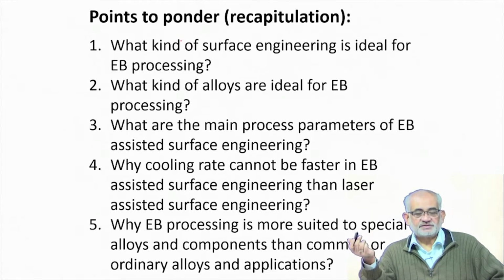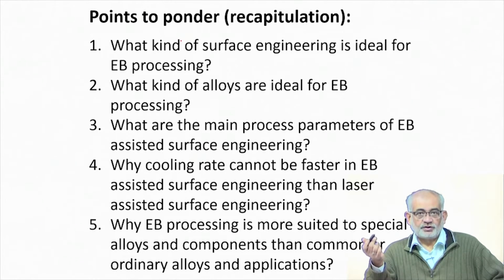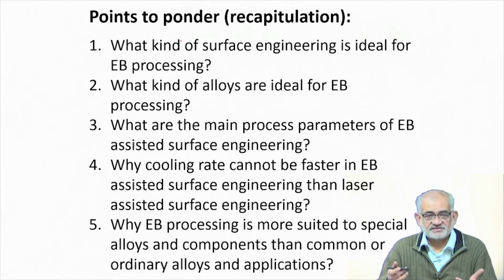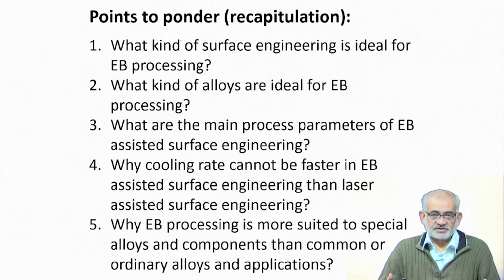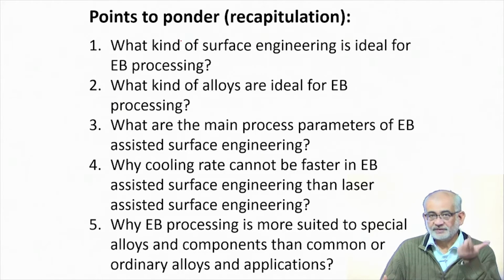And the biggest possible surface engineering application could be, for example, cladding or simply surface melting, because melting and rapid solidification, because of the rapid heat extraction during the solidification process, allows a very small grain size, or high nucleation rate, low growth rate. In the process, we actually end up getting very small, tiny little crystallites throughout the surface, and they don't grow much, so we get a large grain refinement effect.